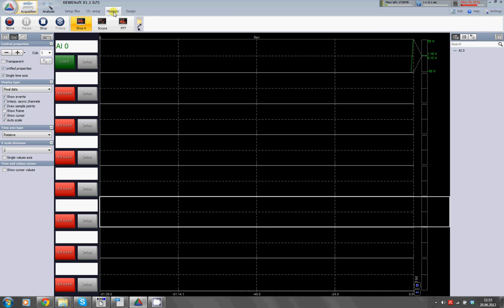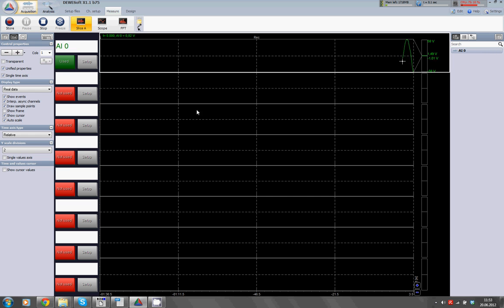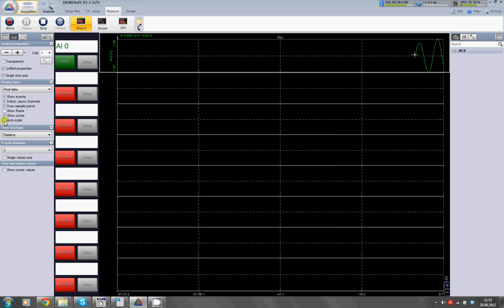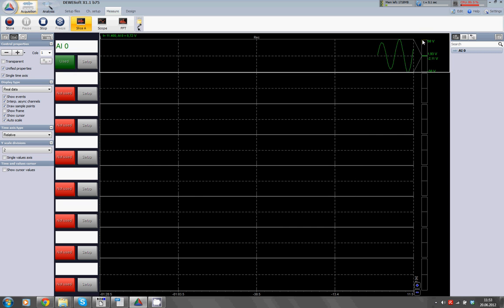Additional features you will find in the measurement screen. We added in our standard recorder screen on the right side an auto scale. We can switch on and off the auto scale functionality, which shows you the total range on the right side and the range which is used for the graphics. So this is also a nice feature. Whatever signal gets in here, you will have a very nice graphic which is dependent on the min-max of the input signal. Due to the high dynamic range we have, you still have the total range, but within that you can go down to 160 dB of resolution, which will show you even microvolts.